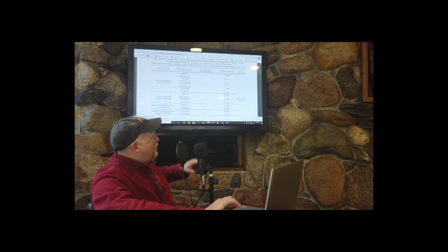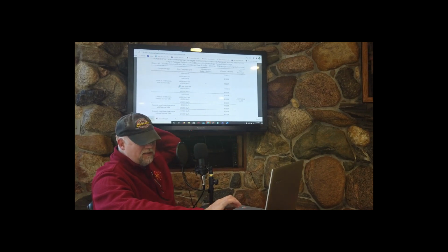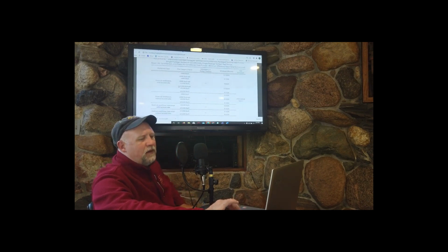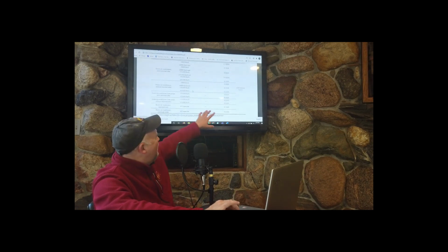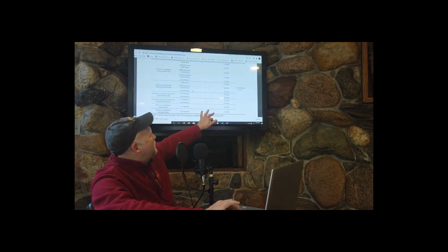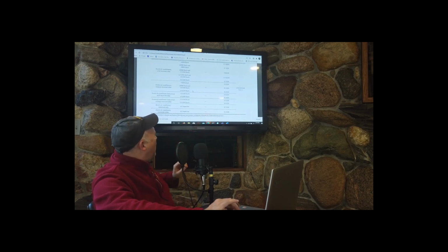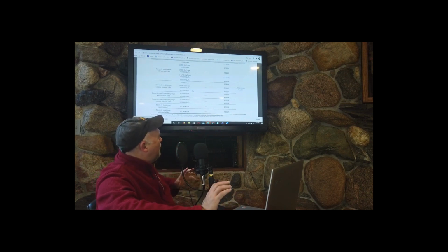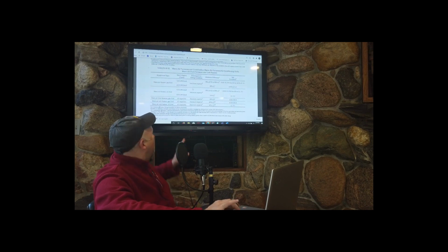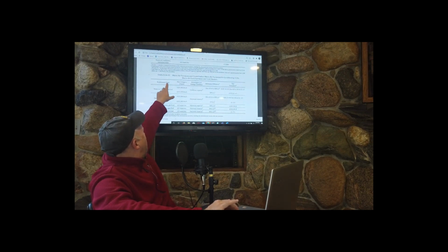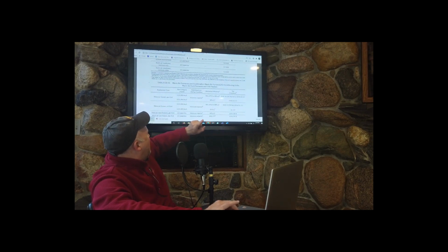So in the handout notes, I converted this EER, this energy efficiency ratio, to kW per ton. This EER has to do with BTUs of energy transferred versus BTUs of energy consumed, and I'm just a fan of thinking all of it as kilowatts per ton. All right, now table 6.8.1. This is a good one to look at and to know.